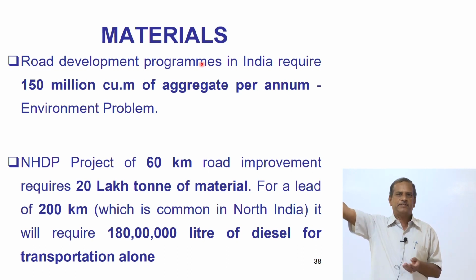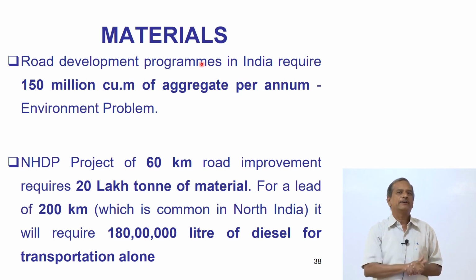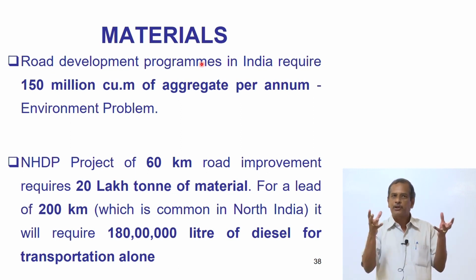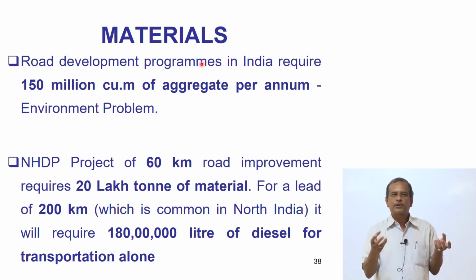If you go to the northeast, you will not get good quality aggregates at all for road construction. If you go to the Andaman and Nicobar Islands, the aggregates there absorb moisture. The water absorption may be more than 2%, and we permit up to 2%. If it absorbs more water, it will lose its load carrying capacity. If it is used for bituminous construction, the binder will strip off from the aggregates. So you will find potholes, cracks and rutting failures.